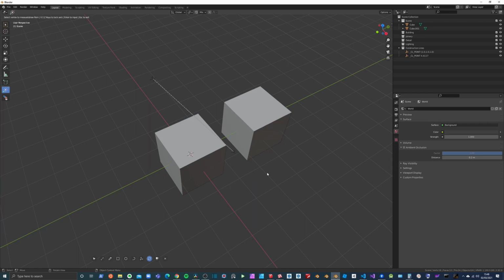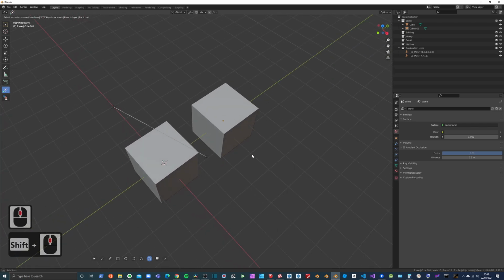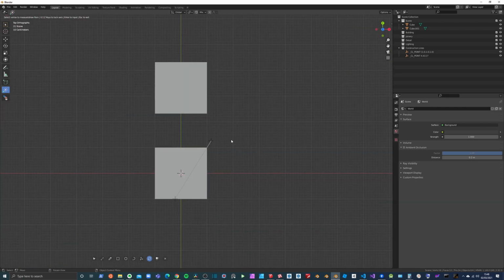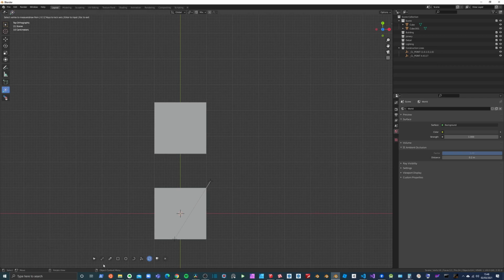Now, another feature, as we're on the subject of guides, I jump into top view. I'll select my guide here, and off of an edge, if I start to build a new guide and I hit Alt, that will turn the guide into a horizontal guide.